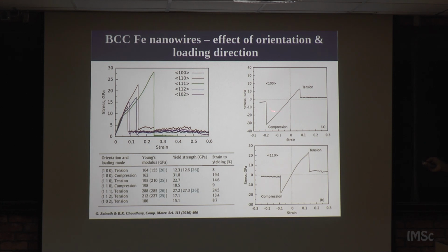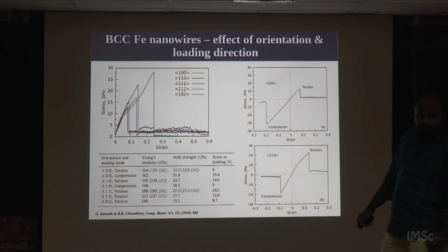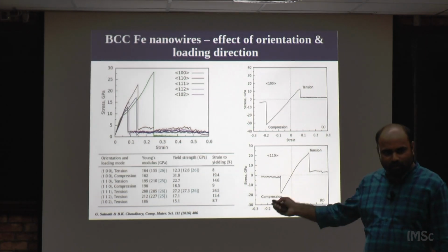So, there are also differences in terms of tension. Yes, exactly. Until here it is perfect, nothing is there, but once it reaches a certain value, depending on the orientation, dislocations or twins nucleate, and further deformation continues by those defects. No, but I will tell you why. Yes, I will show you how it breaks also.